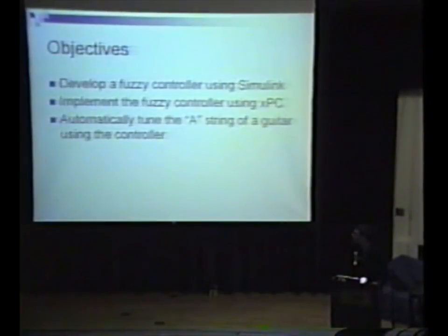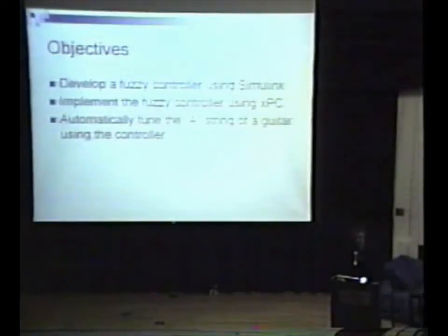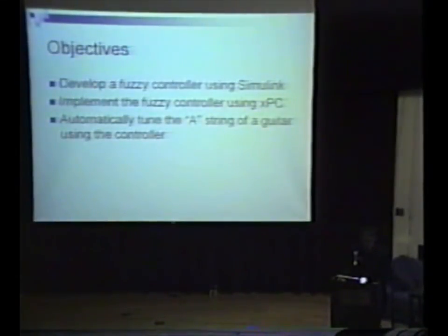The objectives of this project are to develop a fuzzy controller using Simulink, to implement the fuzzy controller using XPC. XPC is a real-time operating system developed by MATLAB. And then to automatically tune the A string of a guitar using this controller.